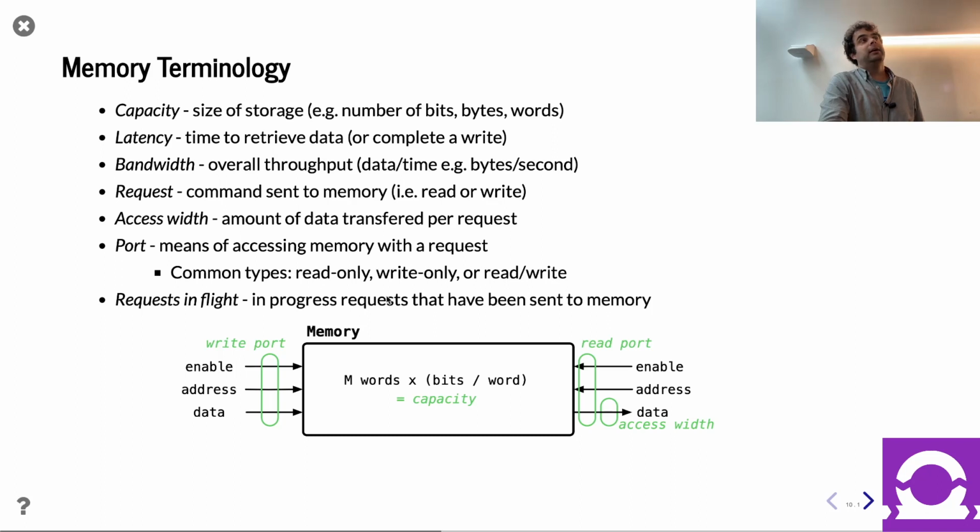On a BRAM, you often have 2 ports. If you need 4 ports of access, that's not going to fit in a BRAM because there are too many ports. But if you can get your access needs down to 2 ports, then yes, you can use a BRAM. So that corresponds to the same constraint. I said 2 ports is doable and common. More than 2 for a given low-level memory is going to require some cleverness. We'll talk about that later today, about how to handle it once you have that many ports.